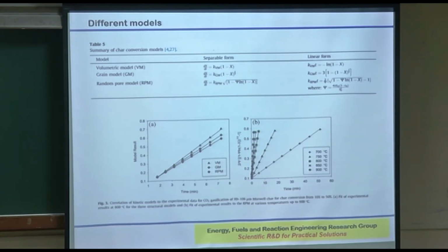So the volume reaction means what? As I say, the entire volume, including pores, the volume inside the pores and outside, will react. So if your experimental data matches with the volume reaction model, then that means the volume reaction model is valid to describe the gasification behavior of that particular char.